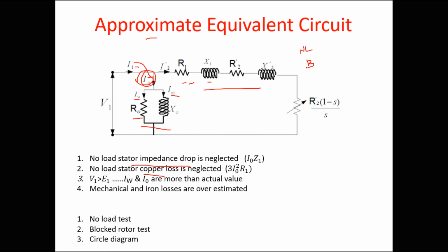And we have discussed the number of turns available in the induction machine, whereas in a transformer we represent that as the number of turns on the primary and secondary, and here we have to include the winding factor on the stator as well as on the rotor. So we call the number of turns on the induction machine the effective number of turns on the stator as well as the effective number of turns on the rotor. And for drawing the approximate equivalent circuit we are going to segregate, that is, rearrange the shunt and series branch parameters. First is shunt, and next we combine all the series parameters together.